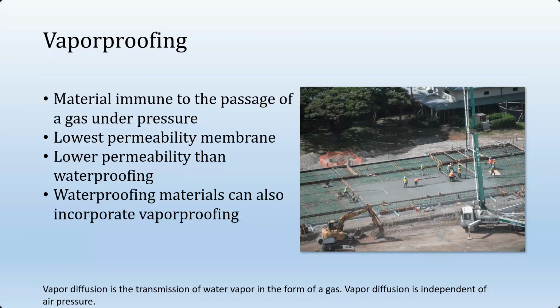Now, one thing I always point out is that vaporproofing is not waterproofing. These products are not tested nor recommended for use when we are going to experience high hydrostatic conditions. So I always get a little put off when reviewing drawings where both waterproofing and Blindside are tying into a vaporproofing. I always get a little suspect of that, just knowing how high hydrostatic conditions act in these types of conditions. So just keep that in mind.